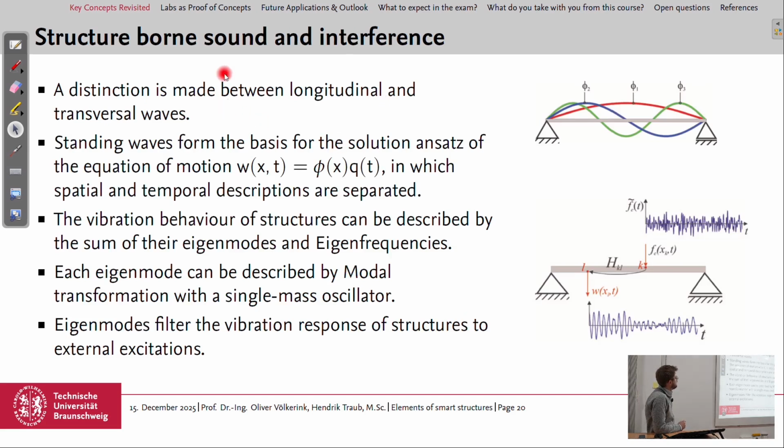Then today we started with structure-borne sound and interference. We made a distinction between longitudinal and transversal waves, had also this small experiment for longitudinal waves here in the lecture, and got to know that standing waves form the basis of the solution ansatz with the separation ansatz, where we have the solution for the equation of motion consisting of 2 parts, the spatial and the temporal description.